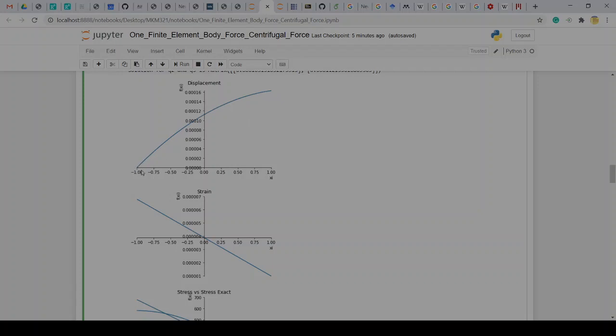Well, first off, the point where it's attached experiences the whole body force acting, the entire loading due to the body forces of that entire structure is being resisted by the edge around which it rotates. So that will see the highest load, and the load will decrease as we go towards the right edge. At the point on the edge of the other side, there's essentially no body force acting on the remaining material onwards, because that's the edge of that bar. And so we expect to see the loading highest here.